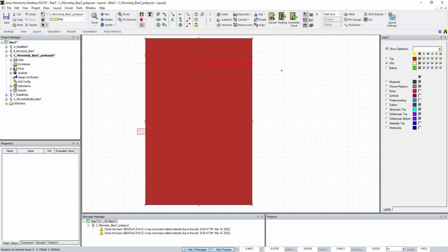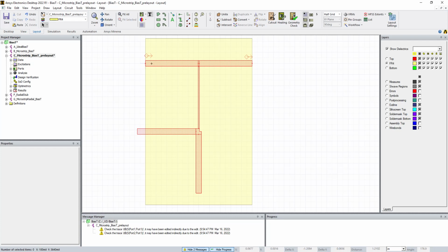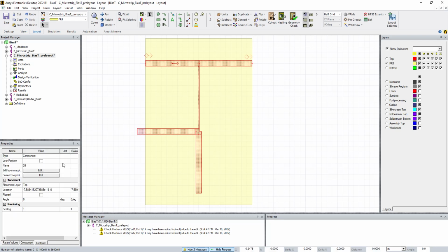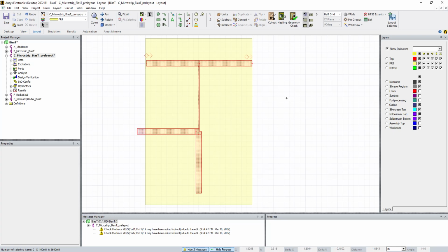Then we have to adjust that part there, because if I hit Control M, oh, look, see what I did? I didn't do that right. So we want W trace offset, comma 0. Then we're going to lock it. Don't forget to lock it. Now we hit Control M, and it adjusts everything over. But now this guy is hanging over by twice the trace offset. I have to move it a trace offset to get here and move it back to another one.